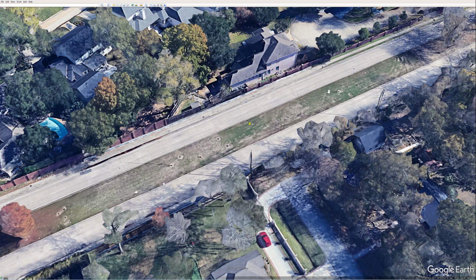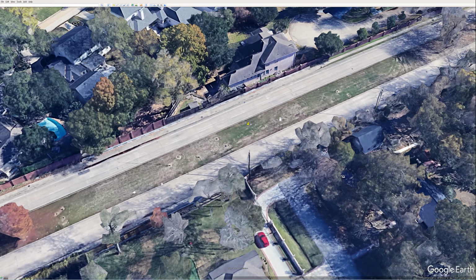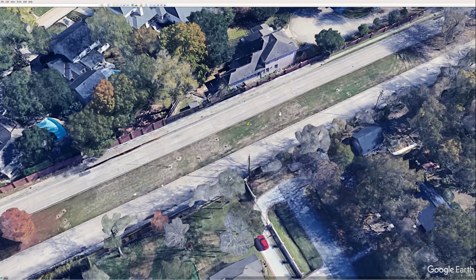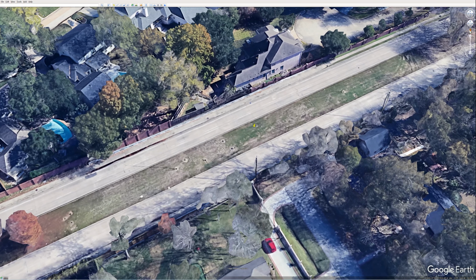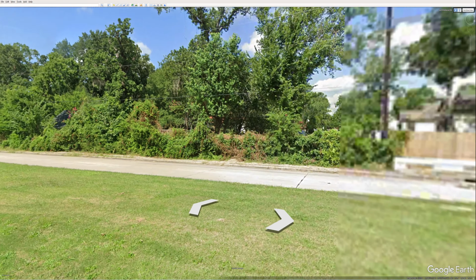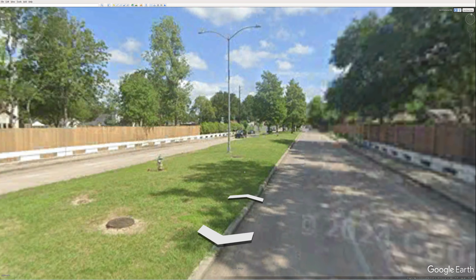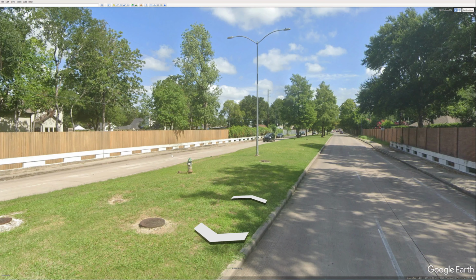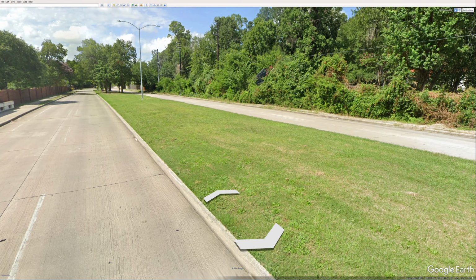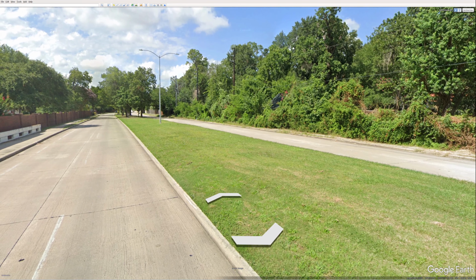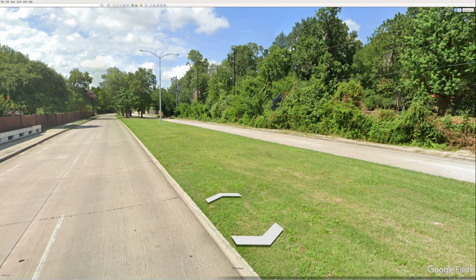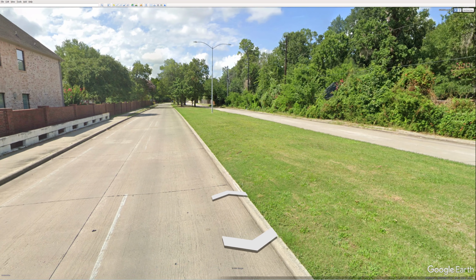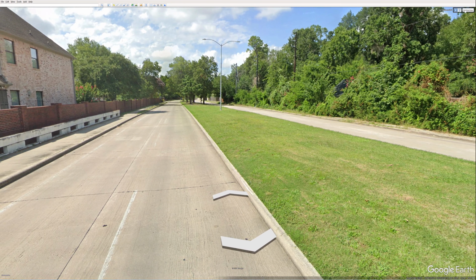This is a road in Houston, Texas, and as a reminder, Beyond Typicals can do a lot of things, but the road has to be straight and mostly unchanging to get the best results, especially when you're compositing. And so we have this road. I can jump down to Street View to get a better look at it. So we have 2 lanes in each direction. We have this grassy median with some lights, and we're going to simply push a new lane in each direction. So we'll have 3 lanes and shrink the median. Again, nothing complex here, but I just want to highlight how you can use construction phasing within Beyond Typicals.